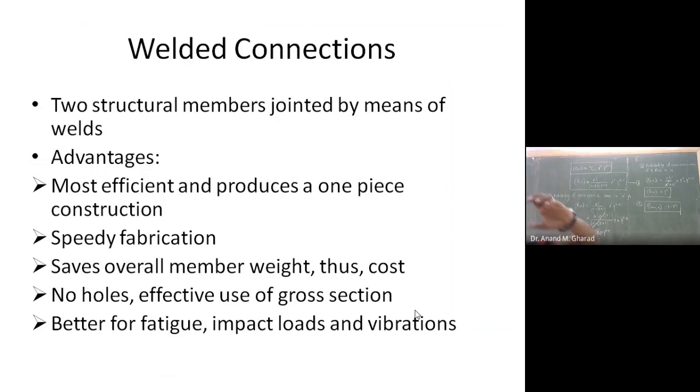What happens then? The material of the member itself is getting melted. No other additional material is used to perform the welding, right? So it has melted, now it is allowed to cool, and once it cools, it gets welded. This is one of the methods of pressure welding, right? Because friction is developing, but pressure is also applied from here.